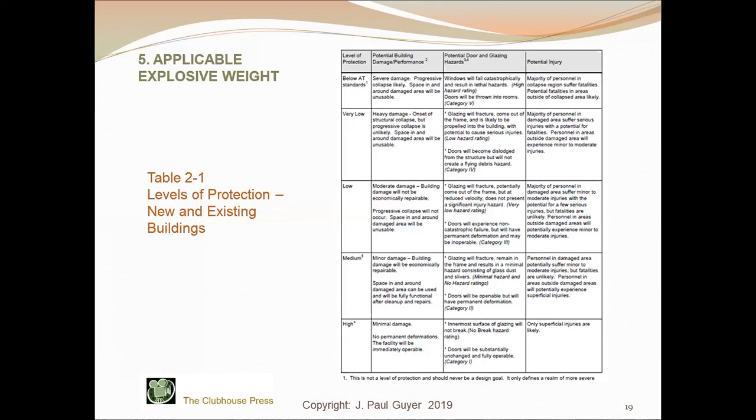But if the building is sufficiently tied together structurally so that the loads that formerly were resisted by that column are now resisted through some other path, through beams and other columns, and it's sufficient to keep the building from collapsing, then that's what's called designed to prevent progressive collapse of buildings.